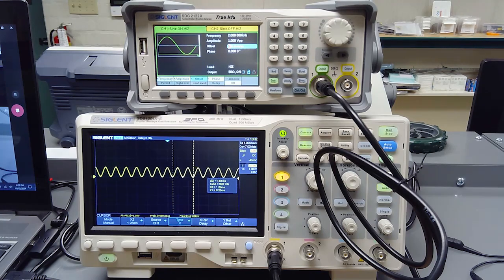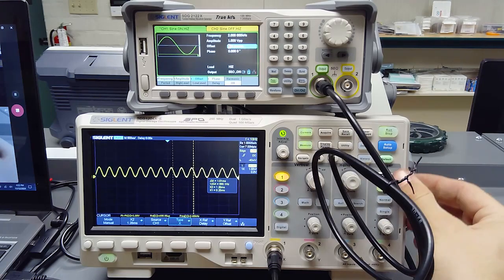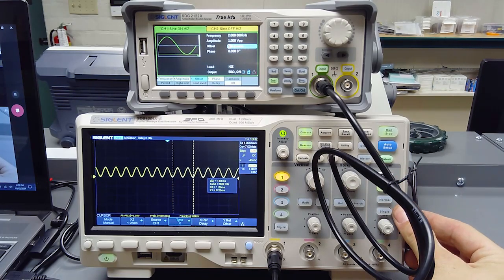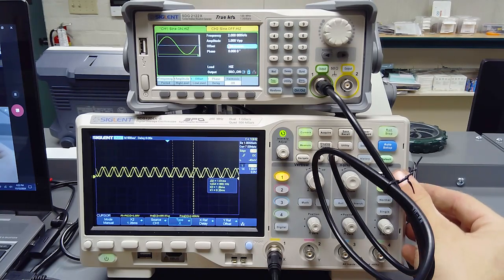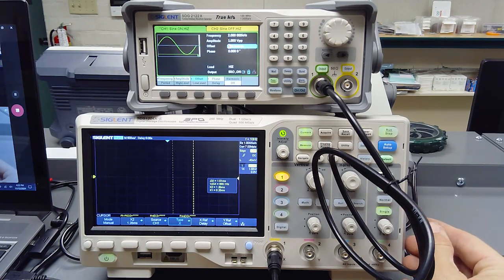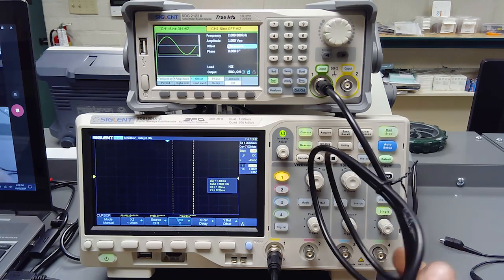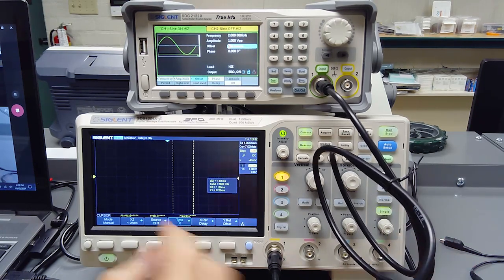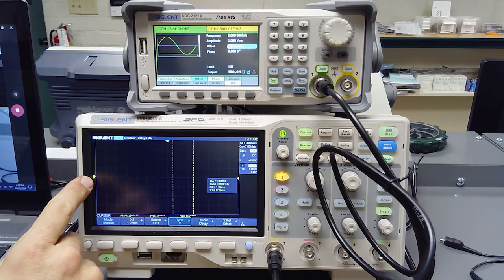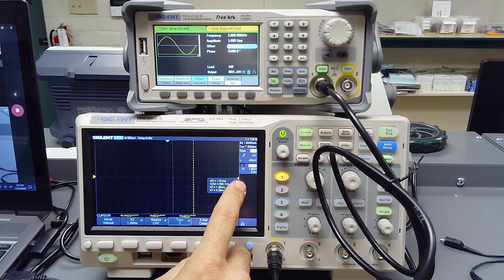So all these scopes have something called a trigger circuit, which is on the right side here. And we can use this to freeze the image of the signal based on whatever parameters we define. So the easiest thing is if we hit single, it'll just capture 1 screen's worth of data. But we have to let it trigger. So the reason it's not triggering is this bottom knob is called the trigger level. And like I said, the triangle on the left is where your 0 is for channel 1. But this right triangle is where it's going to trigger.